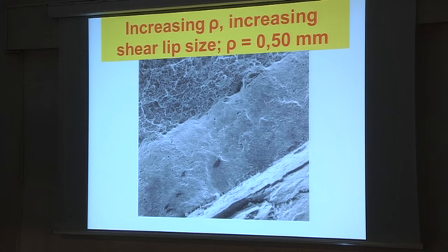And so the whole material between this one and the corresponding line on the other side is deformed. So even if the final surface seems smooth, the mechanism of plastic deformation that goes on below that is much, much, much more intense.